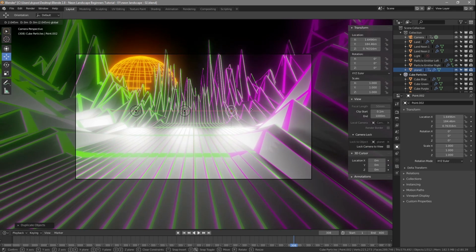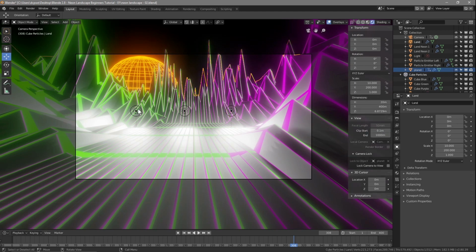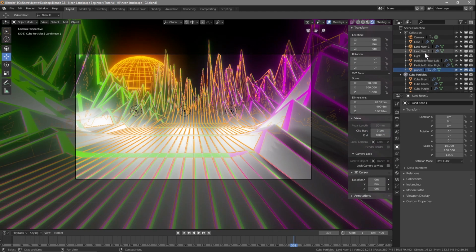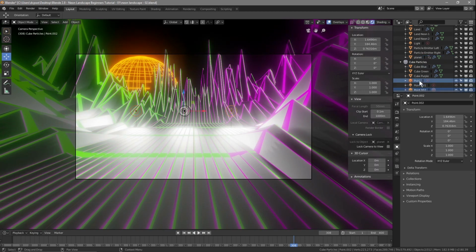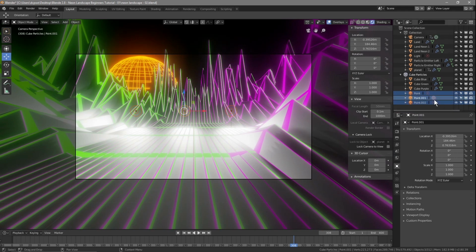So we've got these 3 light sources, and we need to adjust them and change the colors. Let's see, where are the lights in here? They're all going to be down here. So grab all 3 of these point lights. Select the first one, hold down the Shift key and click the bottom 2. So you've got all 3, and drag them into the collection above here. Now you've got all the 3 point lights.